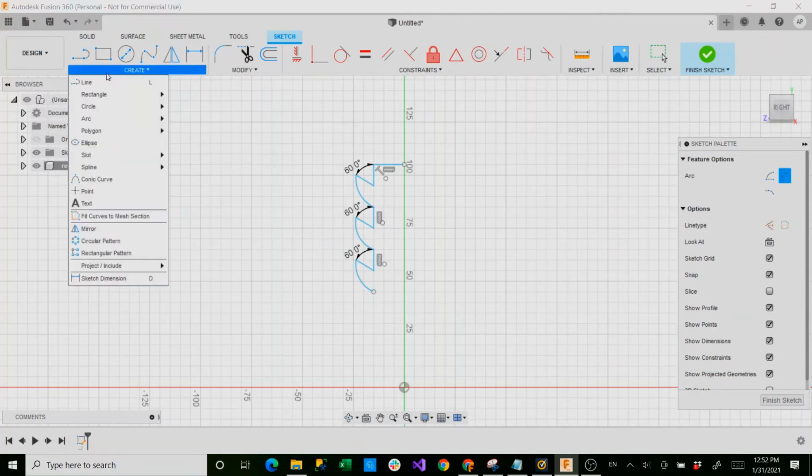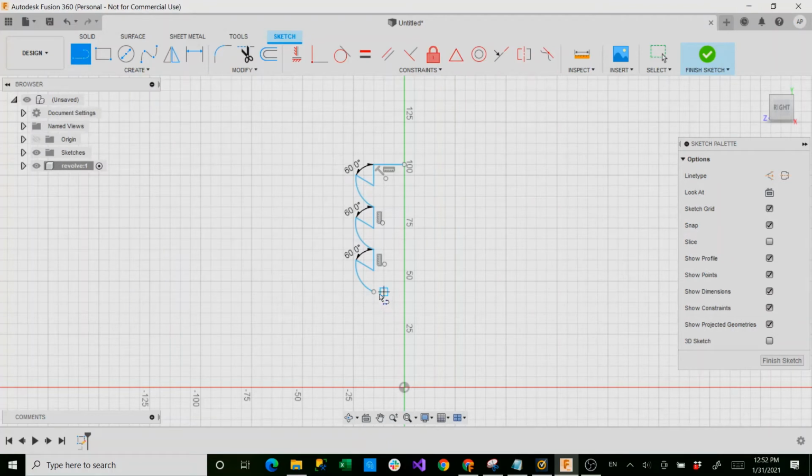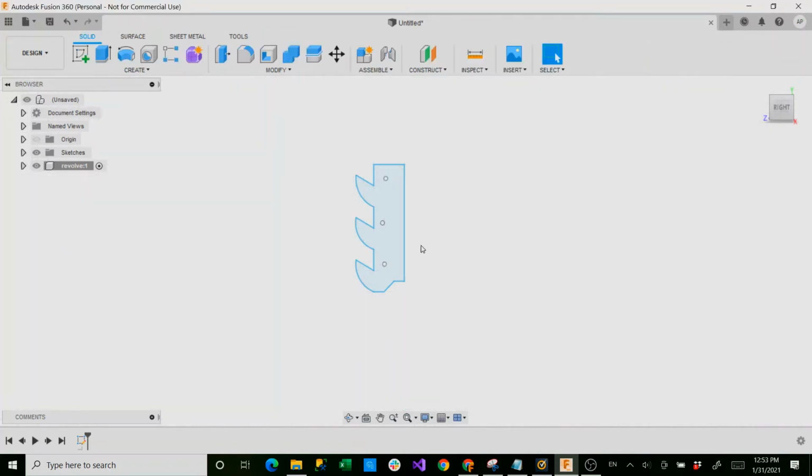Now with that finalized, we can again create our line, except instead of making a downward angle and an angle at an angle, we'll just go over horizontally, go up to there, and then go back to our axis here. And then to finalize this, we'll go up to this first point here. Now as you can see, it finishes it off. We'll hit escape to exit our sketch feature. We'll select finish sketch. As you can see, if you rotate around, we have a face here.